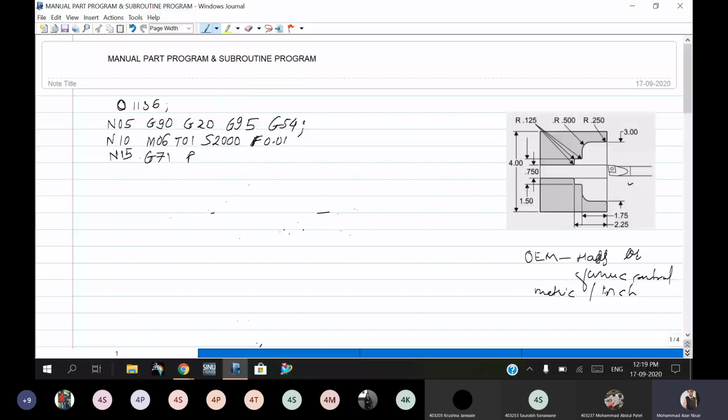Your cycle starts from which line? So 20 is the sequence number. Okay, and then when will it end? Don't write Q yet; make some space for this, because we don't know how many lines it requires. So this will be your N20, so you have to write P20. Your cycle starts from this sequence number N20. Then Q, write it afterward. What is the end of your cycle? You have to write that sequence number.